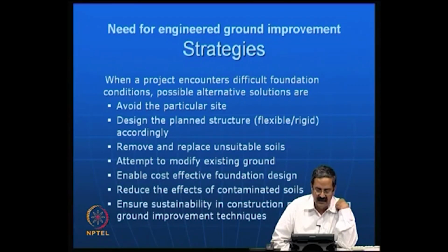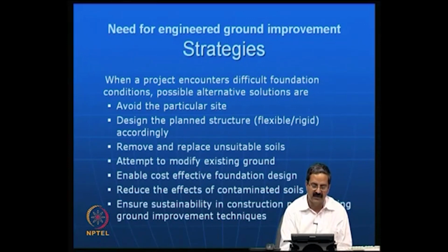So, the other best way is to attempt to modify the existing ground. In fact, this is where ground improvement techniques come into the picture, and in a significant way one can modify the existing ground to what you want. In terms of performance, I want only a very few mm of settlement instead of 100 mm. So, one can use some modifiers or reinforcement and change the state of the existing ground, so that the ground is improved and can be used in a very confident manner. You have a lot of techniques for this that we will see.